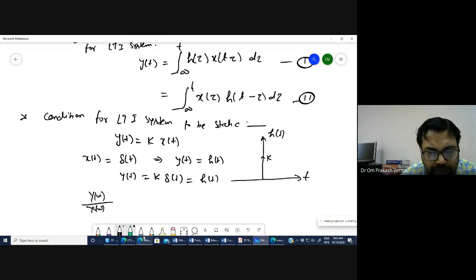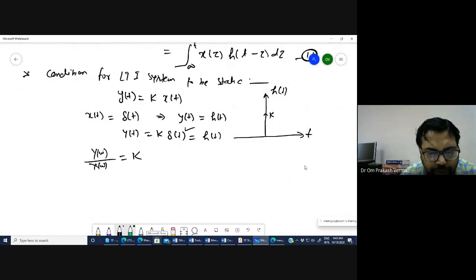So the Laplace transform of this is 1. So you just put in y omega, so it becomes k. And when you plot it, this is x omega. X omega is nothing but the 1. So it becomes h omega. H omega is this k. And when you plot this with respect to omega, this k is represented like this. This is the h omega.